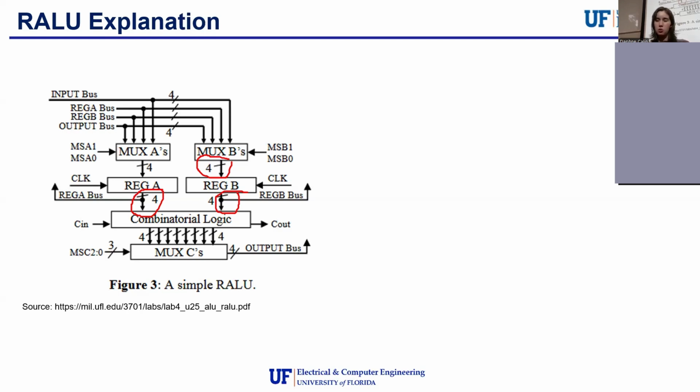It says to have output pins for many of the internal signals, right? So you can actually debug them. But when it comes to actually programming to your board, it would be best to remove these signals, because I think there is some issue with how you normally set unused pins as tri-stated in Quartus, right? But again, this is not completely verified. But I noticed that it appeared as if some of the things selected as output pins were being outputted on random pins, and in this case it was on the hex display of the